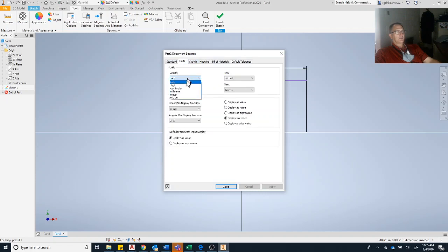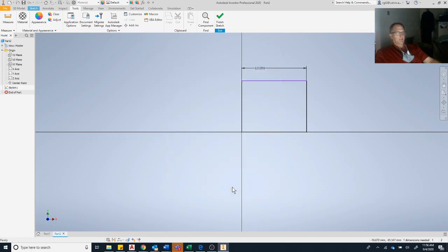Instead of units of inches, I want millimeters. My print, I guess, just says it's in metric, but I'm going with millimeters because that makes the most sense. I don't think this thing's in meters, unless it's like a parking ramp structure. Pounds, mass, whatever, that's good enough. I just got it in millimeters. So I'm good. Hit apply, then close.